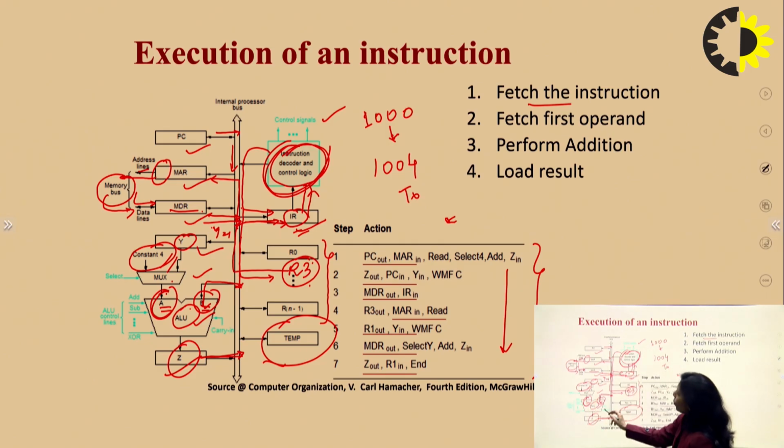Now since the ALU has two input values, one from R1 and one from R3, or we can say the value that was there inside the address pointed to by the R3 register. Now the opcode: when the instruction register got the value, at the very same time the control signal also read whatever opcode was pointing to.